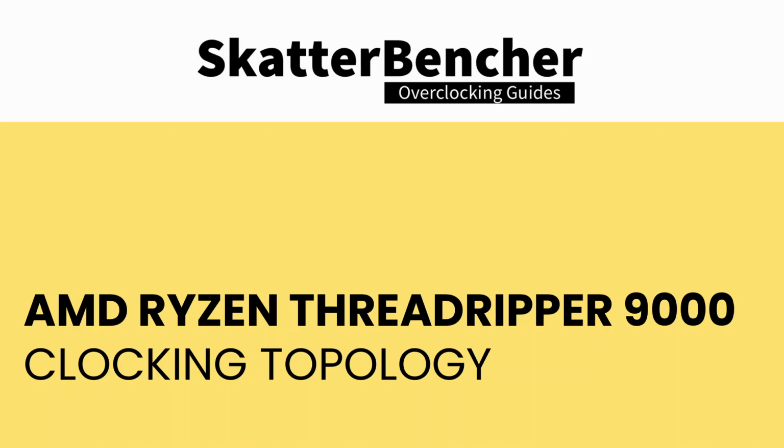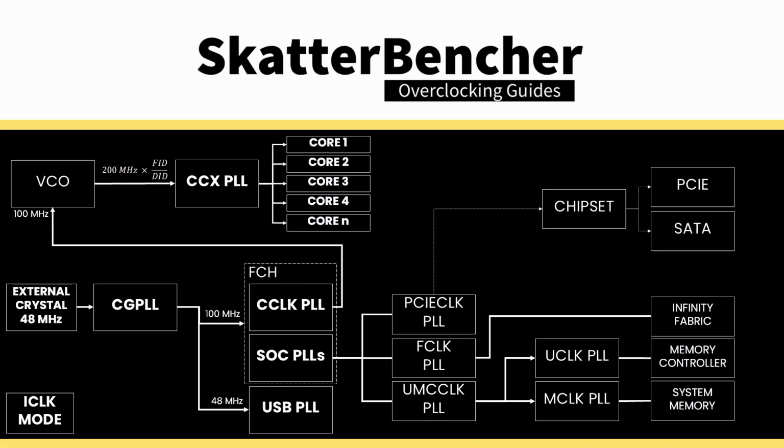Let's have a look at the Ryzen Threadripper 9000 CPU clocking and voltage topology. The standard Shimada Peak platform has a 48 MHz crystal input to the integrated CG-PLL clock generator. The CG-PLL then generates a 48 MHz clock for the USB PLL and a 100 MHz reference clock for the FCH, which contains the CCLK PLL for the CPU cores and several SoC PLLs.